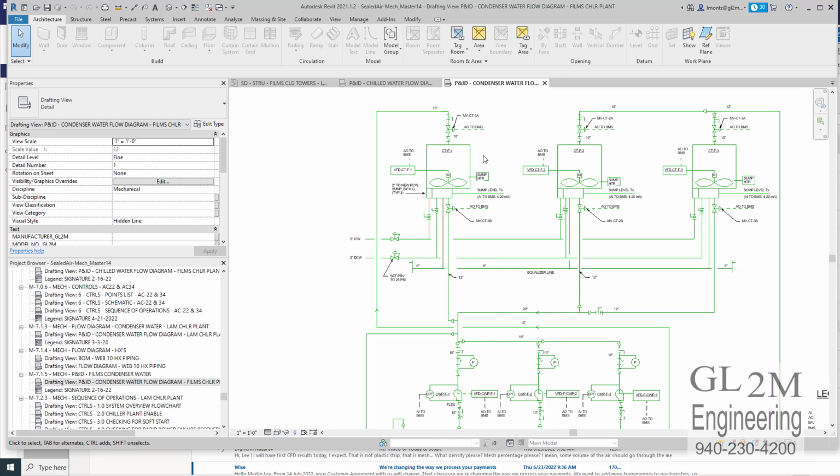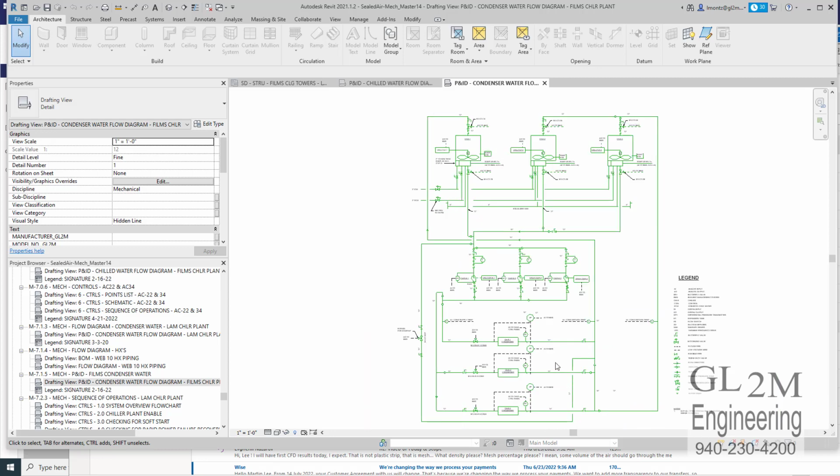These towers have multiple small fans on the bottom instead of one or two or three large fans on the top. So if one fan fails, the cooling tower isn't down, and it can be separately maintained. Rather than taking down the whole cooling tower, it actually can continue to run while the fan is replaced. There's more safeties in here, but I don't want to bore you with the details other than to show you that this is a state-of-the-art chiller plant for an industrial facility.